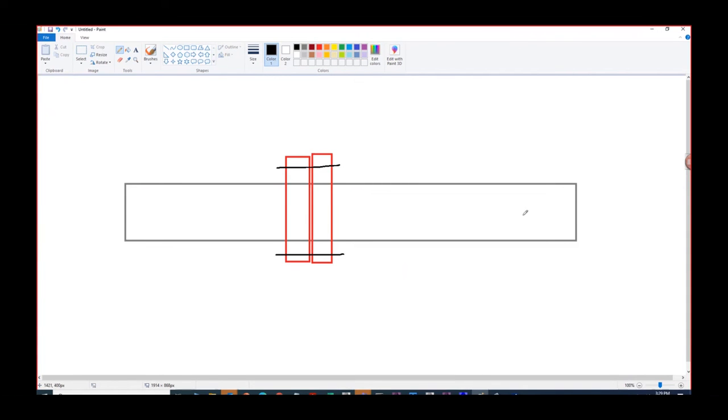Now what will happen? This pipe has to close somewhere, right? But we are not modeling the entire length. We are cutting this pipe at some distance like this, and considering only this small portion. But this axial force due to the closure will always act here. That is the one scenario we need to consider.